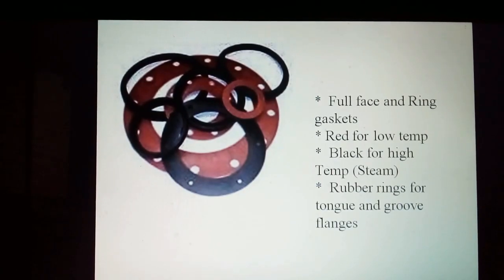Widely used materials for gaskets are compressed asbestos, which is 2 and 5 millimeters thick, and asbestos-filled metal. These are changed after every opening of flanges. The filled metal gasket is especially useful if maintenance requires repeated uncoupling of flanges, as the gasket separates clean and is often reused. A separate video is made for gaskets.